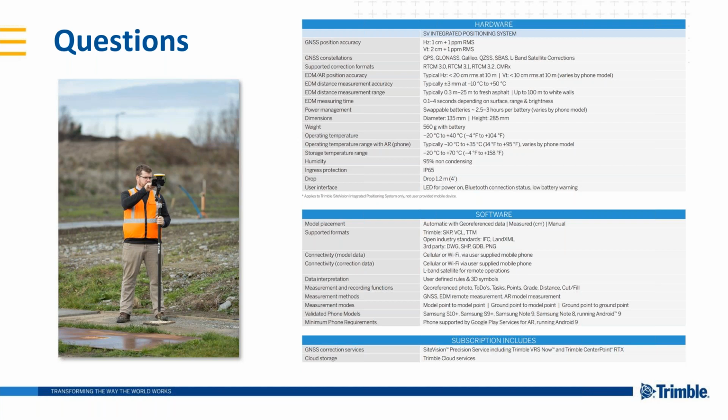What is the distance of the EDM? So I think the typical distance for the EDM is out to 25 meters, but best case, we've had it returning distances out to 100 meters. I would caution people measuring out to that longer range, however, because the accuracy with which you're measuring really depends mostly on how still or how steady you are holding the device.